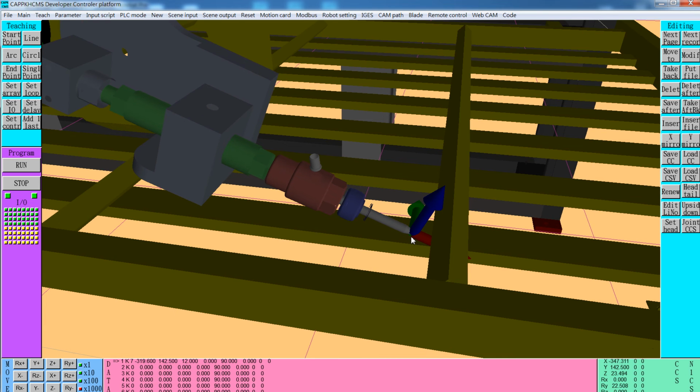This position seems okay if we lower the tool vertically. So we have to lock the first point in these positions. We have to remove the K7 first. Use renew to remove the data in the data field, and change to joint mode, and use line to lock